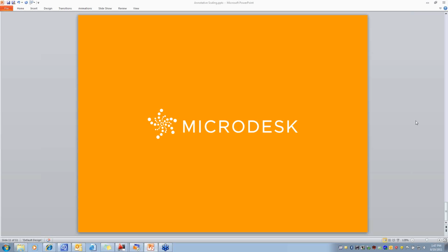All right, we've got another one here. Are there still issues with XREF scales slowing down DWGs or corrupting files? There is still that issue. That was when I showed you the hide XREF scales. That's going to prevent some of it. In the earlier versions, 2008, 2009, that tool wasn't there, so Autodesk has a scale cleanup utility, and that would work to clean up the scales.